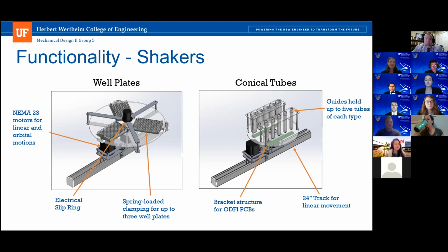Both motors are located on the cart that rides on the shaker rail. The first stepper motor provides the linear motion of the system along the cart using drive rollers, while the second motor provides the orbital motion of the system. The combination of these 2 motors will achieve any motion pattern. So if you'd like to use the linear, just use the linear system. The orbital, use the orbital. Combining the 2, the linear and the orbital, will produce the double orbital motion.